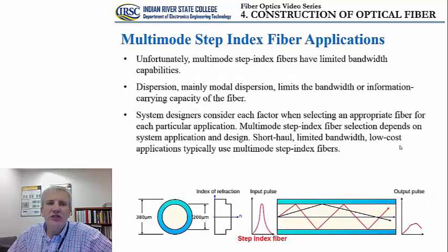What would be the applications of the multimode stepped index fibers? Obviously, due to the fact that the dispersion in this type of fiber is more pronounced, these fibers will have limited bandwidth capabilities, and therefore limited applications. Usually shorter distances would be the applications of this type of fiber.